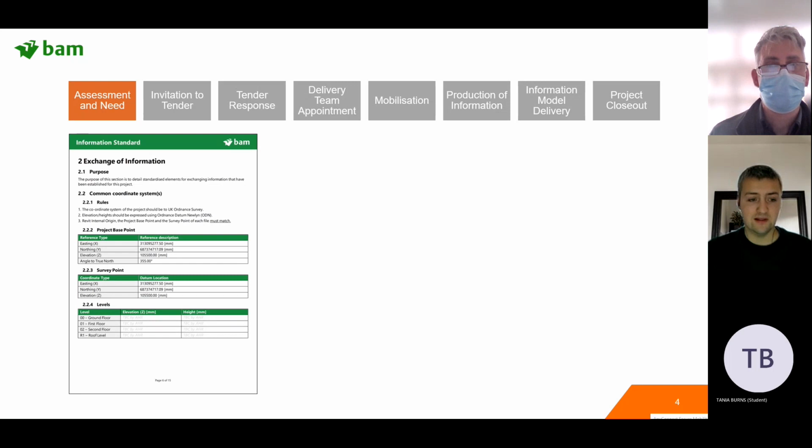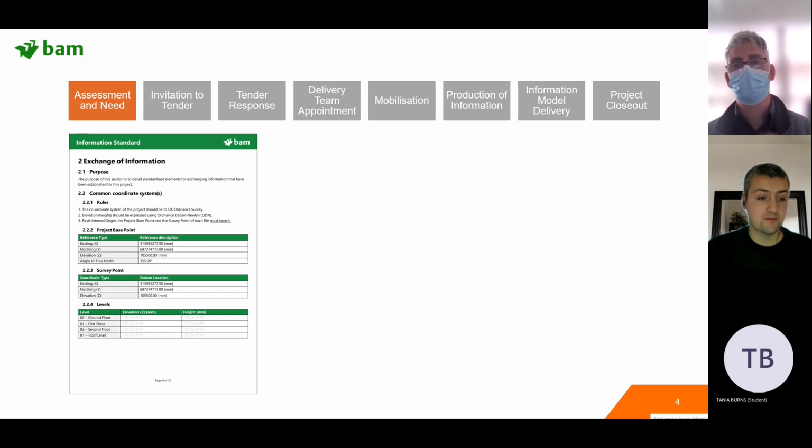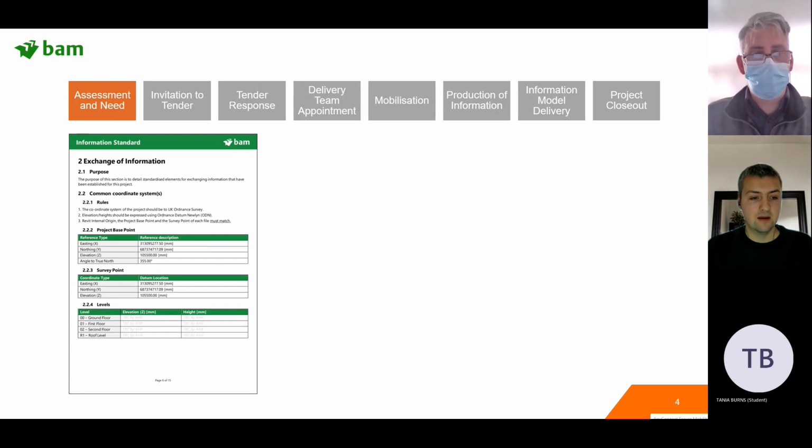So what that means is when you link one model into another, when you're merging the models together, the model just falls in the right place. You don't have to manually move anything because you've punched in the correct coordinates. Surprisingly, this is common sense, but it's often still not done, even on big projects we work on. I'll open a model, I'll try and link in all the other design team models, and they don't come in the right place.